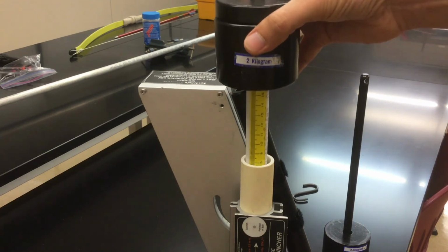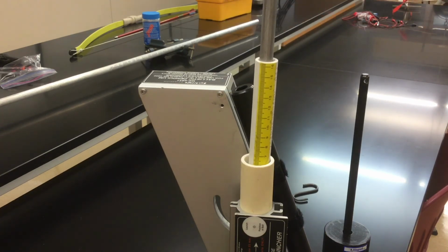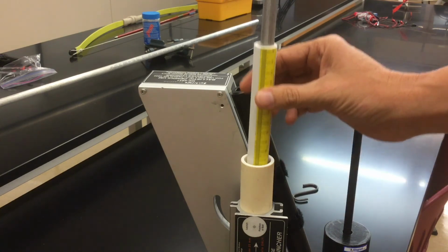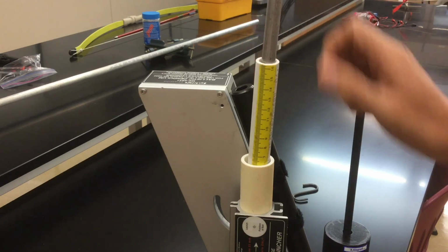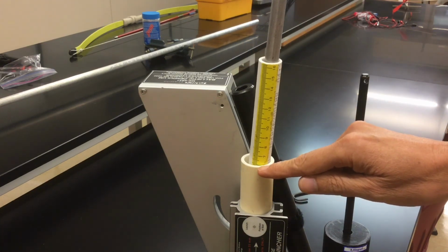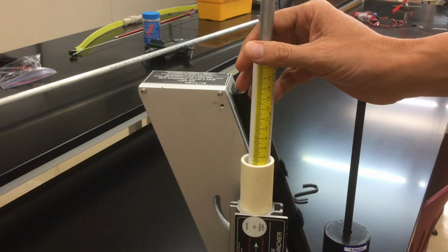So you're going to put force values on the y-axis, position values on the x-axis, and that graph will not include the origin. That's simply because our 0 mark is kind of arbitrary on here, right? When it's unloaded, it doesn't sit at 0, it sits at 6.1. So your graph will have a y-intercept, that's fine.